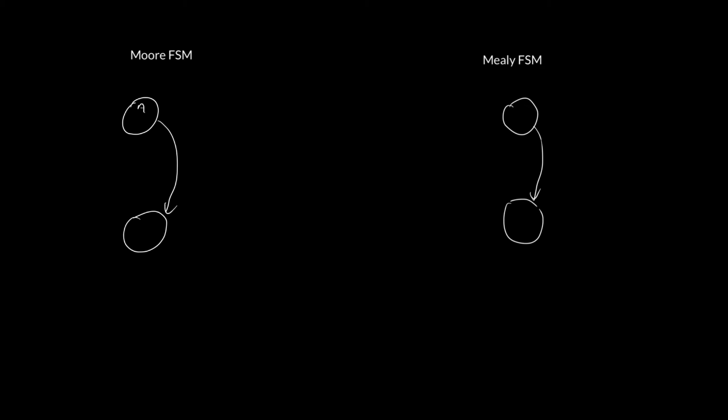For a Moore finite state machine, we label the node by giving it a name, so it could be a letter, a name, a number, whatever. So this is state A, and we draw a line, and underneath state A we represent the output. It depends how many bits of output we have. If we have a 3-bit output, then I need to put a 3-bit number for this state. The number of bits on the output is always going to be the same. Down here gives this state a name, state B, and indicates the output if I'm in this state here.